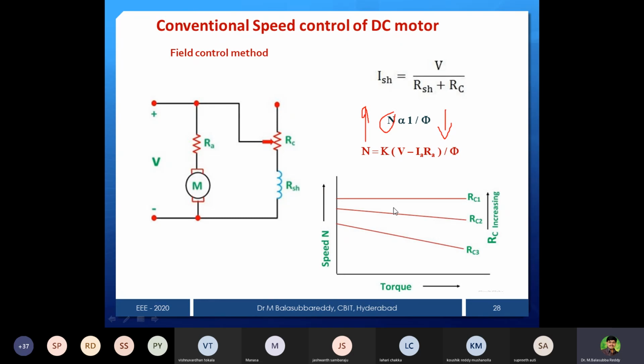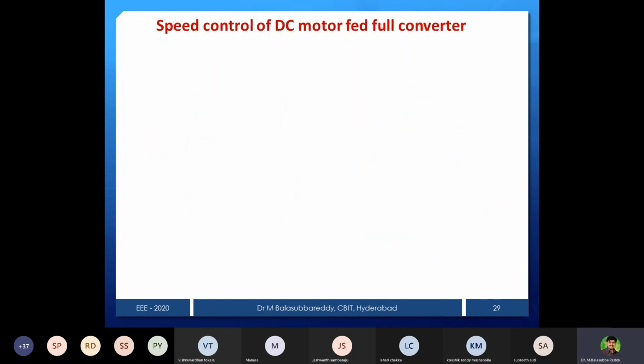This is the characteristic. Now, how are these replaced by our controller? One thing to remember: armature voltage is going to be controlled, and another, field current will be controllable. Voltage control, and current will also be controlled. These two things you can apply using our phase control rectifier. This is a motor with Ra, La and Eb, the RLE equivalent circuit of a motor, represented like this. Now I want to control the armature as well as the field.